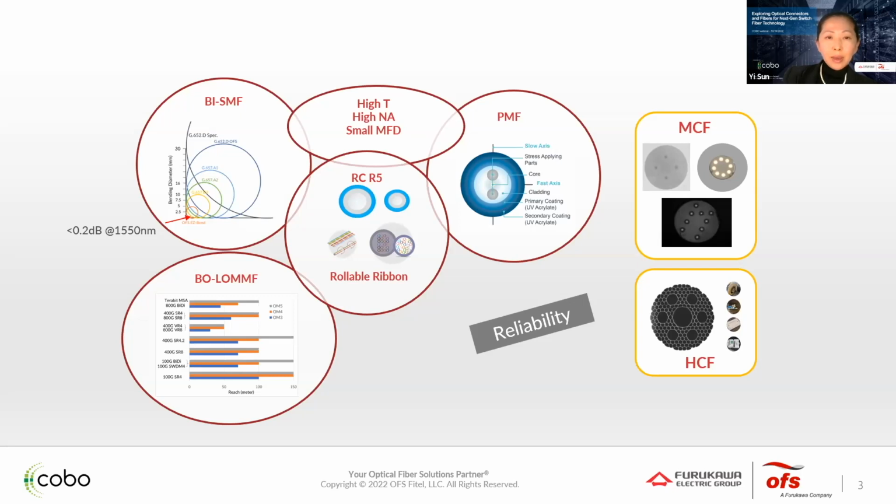Those are wavelength multiplexing using 2 wavelengths. And there's also the proprietary SWDM4, that's 4 wavelengths. So the bending sensitive design fiber and wavelength multiplexing are the approaches to increase the fiber density, optical density.